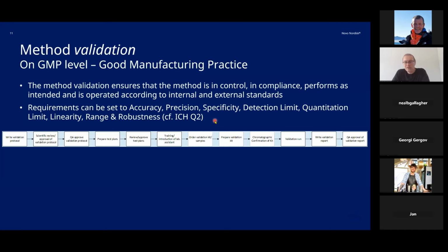If we notice a deviation, then we should record it, and we should immediately do an impact assessment. So this instrument or this method is out of control. When was it last documented in control? What measurements have we taken since we last knew it was in control?